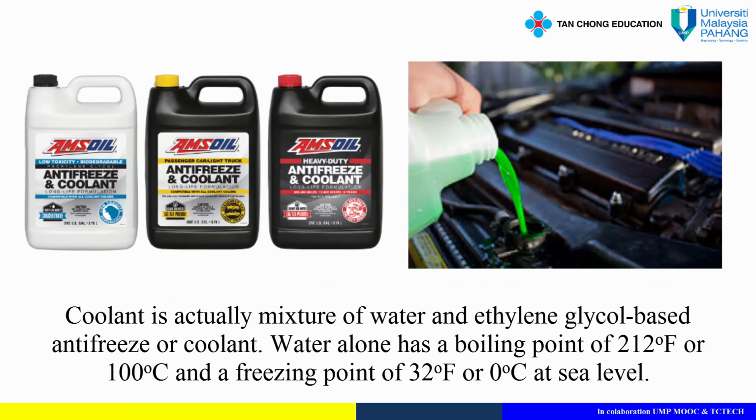Coolant. Coolant is actually a mixture of water and ethylene glycol-based antifreeze, or coolant. Water alone has a boiling point of 212 degrees Fahrenheit, or 100 degrees Celsius, and a freezing point of 32 degrees Fahrenheit, or 0 degrees Celsius, at sea level.